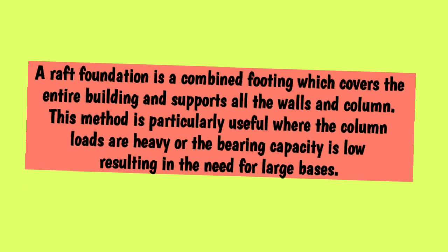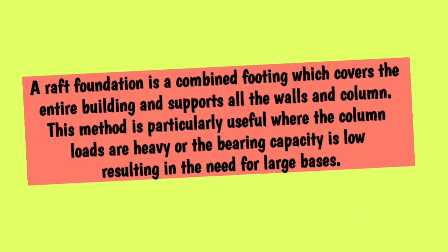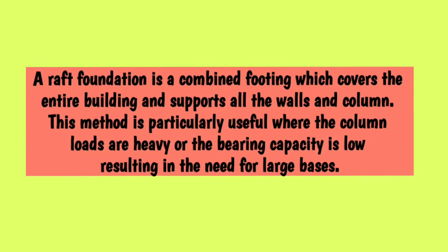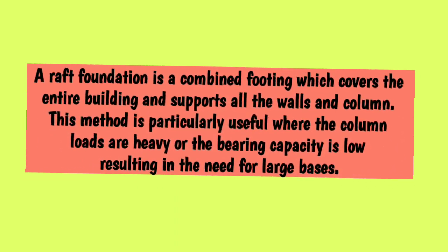Number five, raft foundation. A raft foundation is a combined footing which covers the entire building and supports all the walls and columns. This method is particularly useful where the column loads are heavy or the bearing capacity is low, resulting in the need for large bases.